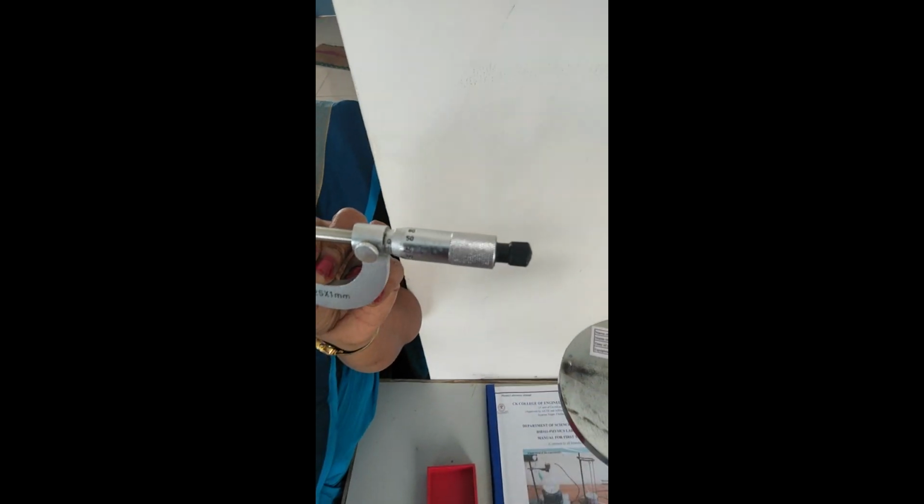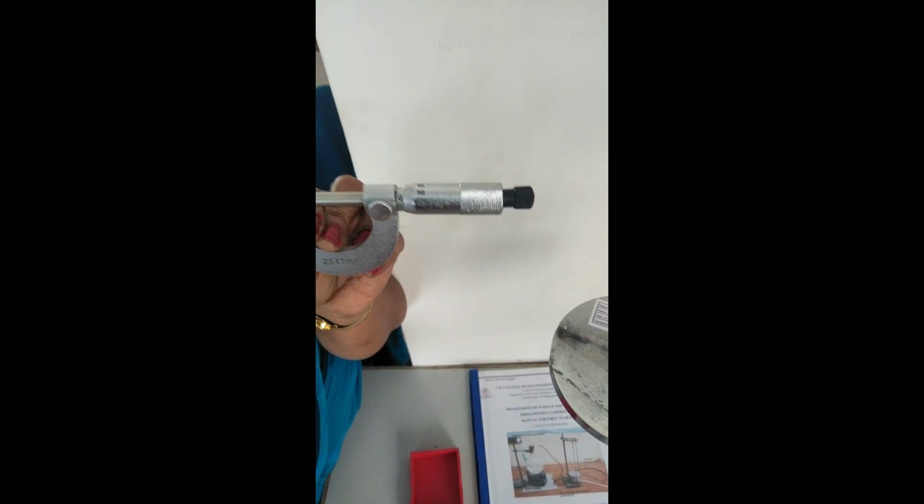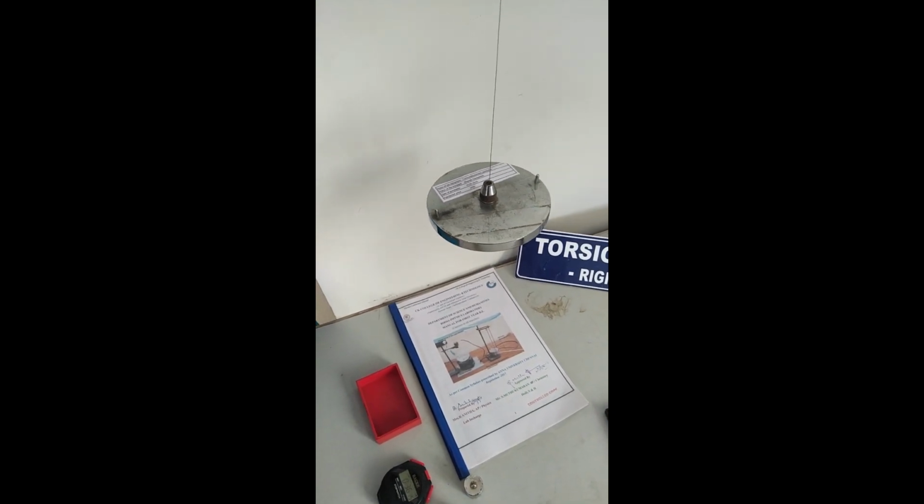One more portion is we have to find out the radius of this wire using the screw gauge. So this is the screw gauge. Before taking the readings, you have to find out the error and correction. In the screw gauge, if these two lines exactly coincide with each other, that is 0 and this line exactly coincide after completing the complete screws, then there is no error. But if I tighten the screw, what happens? The 0 either goes up or down. So there is an error in the screw gauge.